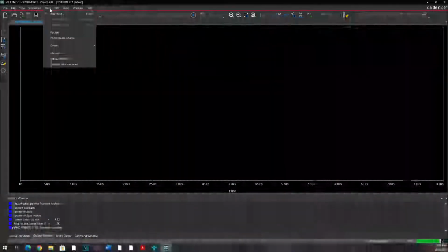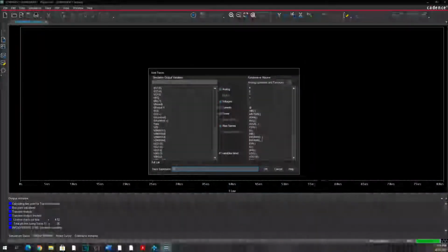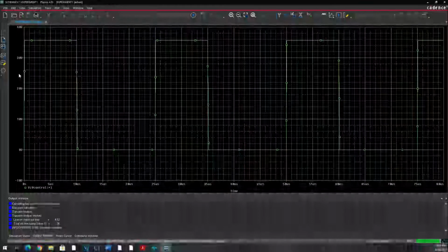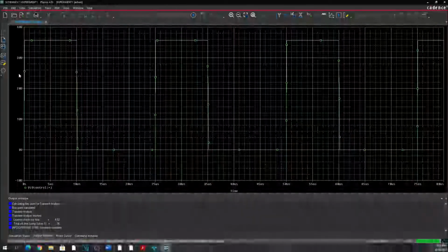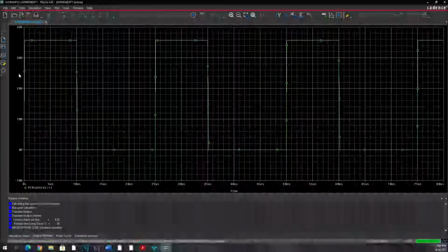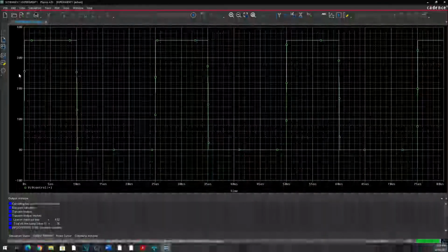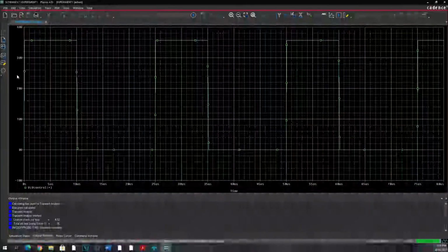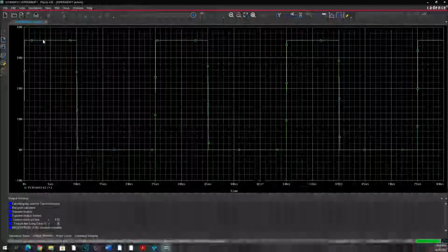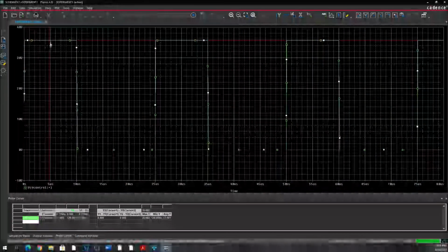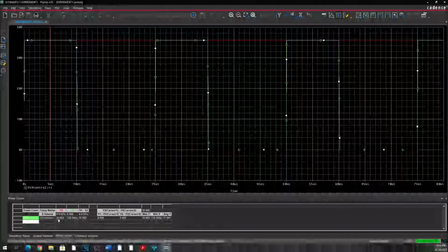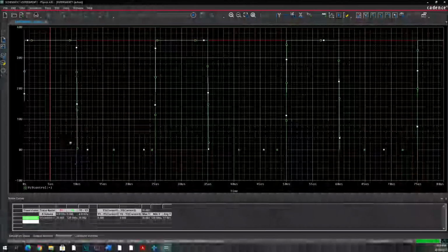So in part 2, we will also test our switch control voltage and load resistor voltage. Let's go to trace, add trace, then V control, positive, and close parentheses. There. In the simulation of part 2, we can already tell the difference between the previous circuit design using S-break as our switch and using a MOSFET transistor as our switch. Now let's measure the peak voltage value in our switch control voltage. Let's click here, cursor on, then here. So in our cursor, we recorded a value of 35.683 volts.